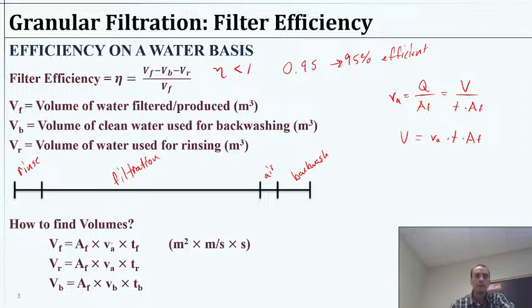One thing you'll notice is for the filtration and for the rinsing, we always load those at the same rate, because we rinse at the same rate that we will filter. Because really we're just starting the filtration, we just have to discard some of that water that's going to come out dirty.